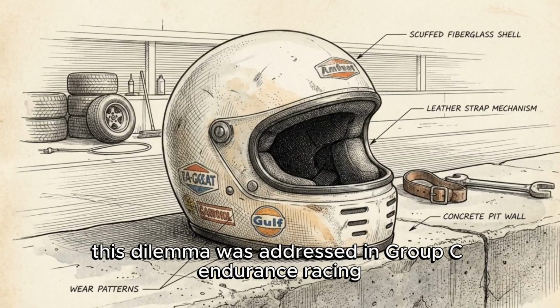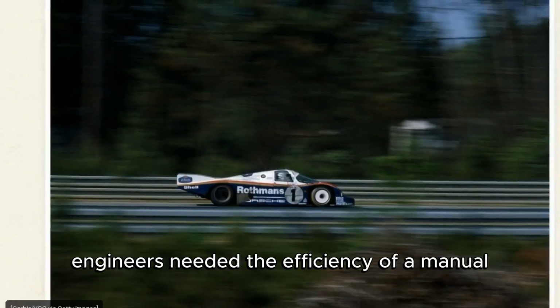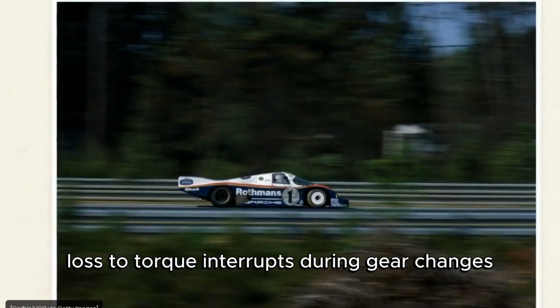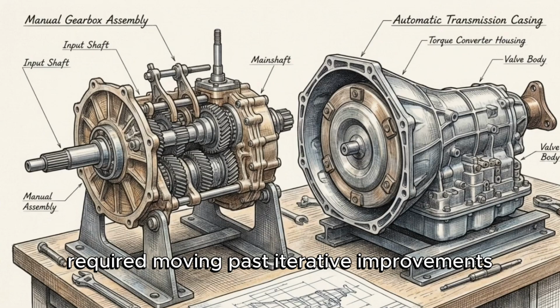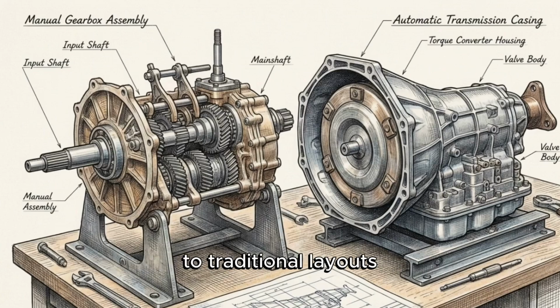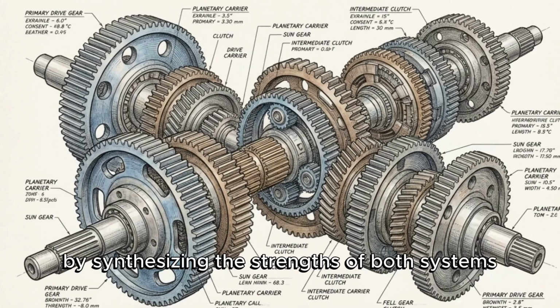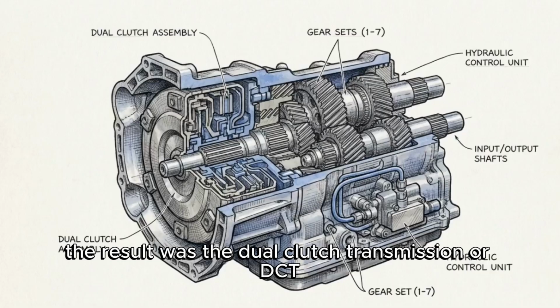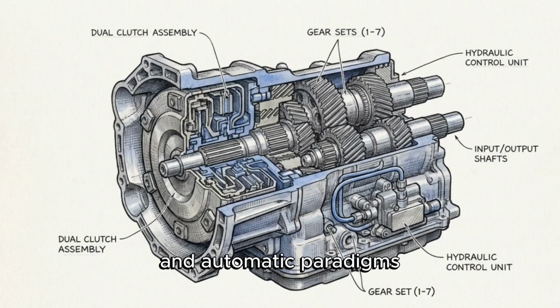This dilemma was addressed in Group C endurance racing. In the Porsche 962, engineers needed the efficiency of a manual, but could not afford the milliseconds lost to torque interrupts during gear changes. Overcoming this dichotomy required moving past iterative improvements to traditional layouts. Engineers developed a different kinematic architecture by synthesizing the strengths of both systems. The result was the dual-clutch transmission, or DCT, a mechanical synthesis of the manual and automatic paradigms.